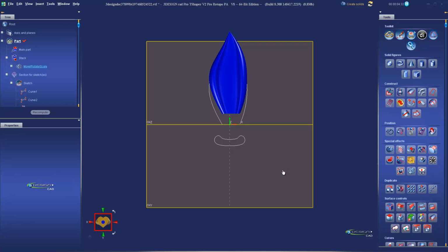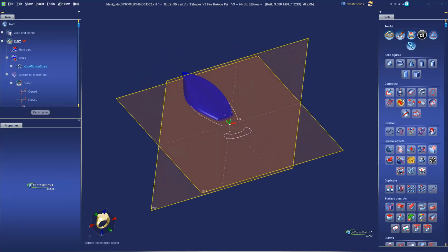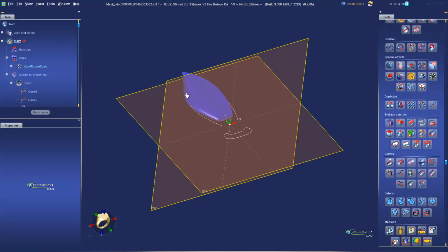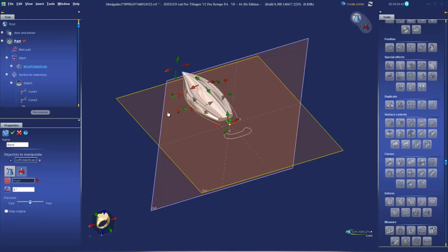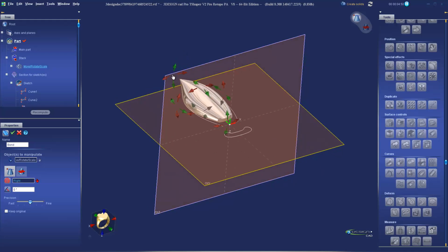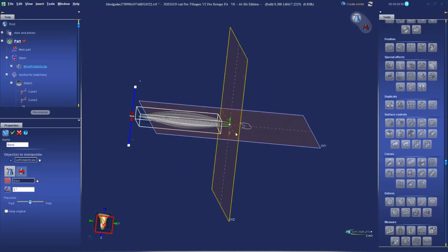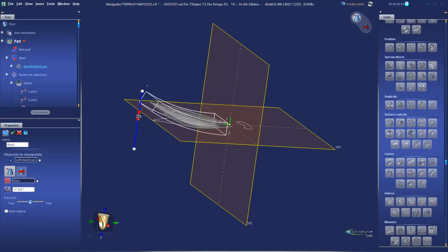And also, before we circular duplicate it, it's much easier if we add tools now instead of having to go back and add them later. So I also want to bend this petal a little bit. So if I go ahead and click on the petal and then bend, this is a regular bend in the deform section. Okay. The direction I'm bending it in is going to be along the green at the tip of the petal. So go ahead and click that one time, and that'll open up the slider. So now we can grab that slider and bend it a little bit.